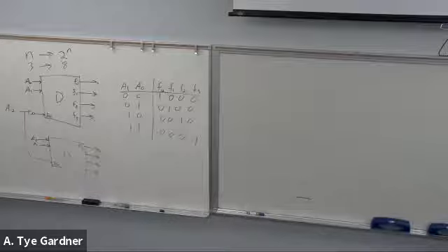Now this one has a little bit of a problem, in that I have lost my ability to enable or disable the whole circuit, right? I can't turn off the 3 to 8 because one or the other of them is always on. So let's say we want to preserve our enable.